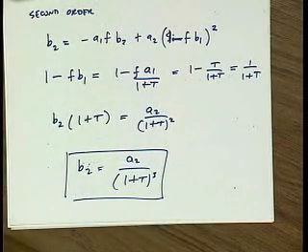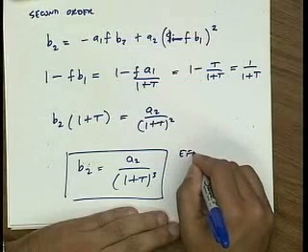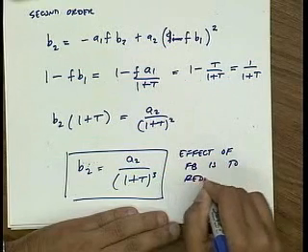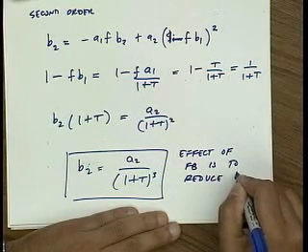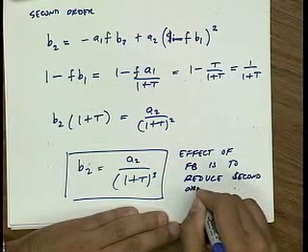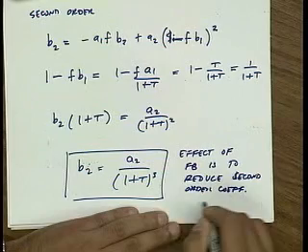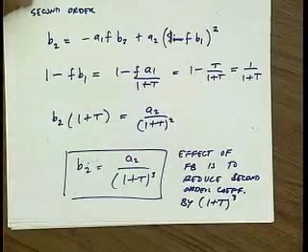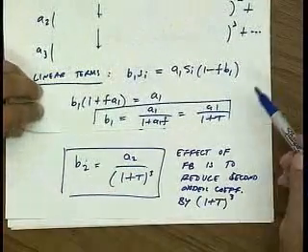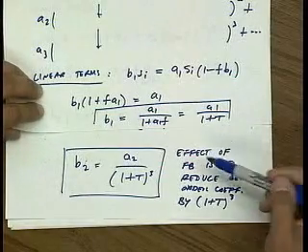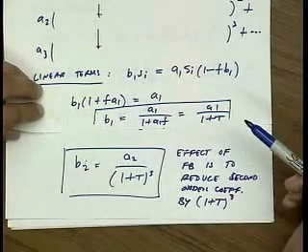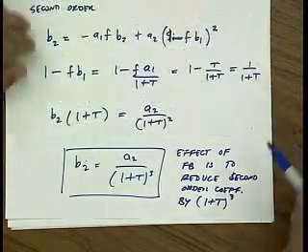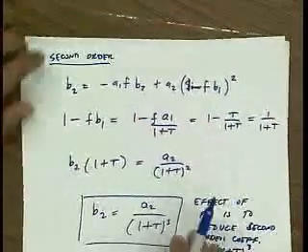Okay? So we see the effect of the feedback is to reduce the second order coefficient by 1 plus the loop gain cubed. Well, that's brilliant, because if we look at what the effect of feedback was on the linear gain, it only reduced the linear gain by 1 plus T. So if I still take the ratio of B2 over B1, I still have an improvement by loop gain squared. So that's really good. Okay, well, what about the cubic term? Any questions up to here?